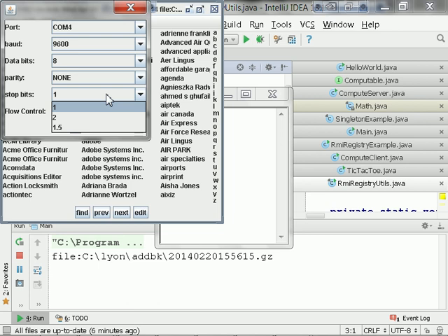And so what that means is it's got a clock in there that says, okay, is there a 0 there? And then another clock comes up and says, okay, is there a 0 or a 1 there? And so it's trying to find out where the center is of the bit as it marches across the wire. That bit clock has to be correct, or else you're going to have a framing error on the receiver. And you can choose the number of stop bits.